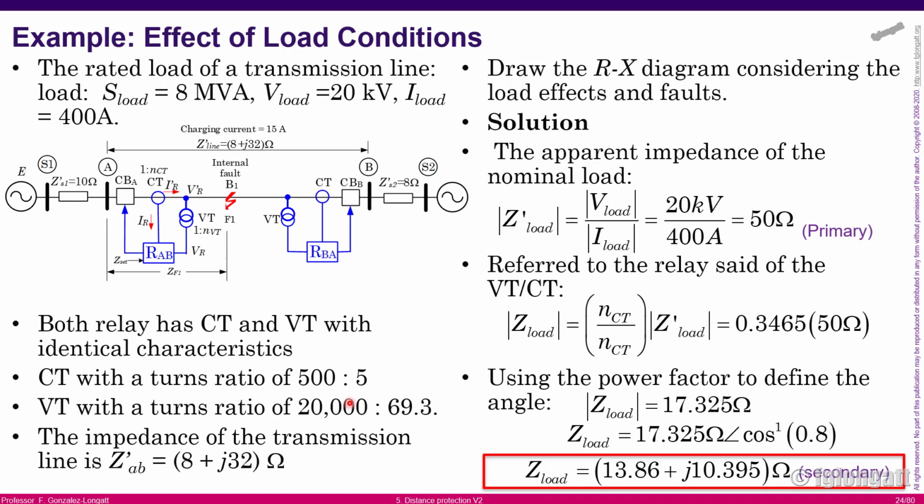Now the interesting question here is we want to create the representation of this system in the RX plane. That is what we want. We want to create the plot on the resistance-reactance plane in order to show you all the effects coming from loads and faults. Okay, what is the first step?